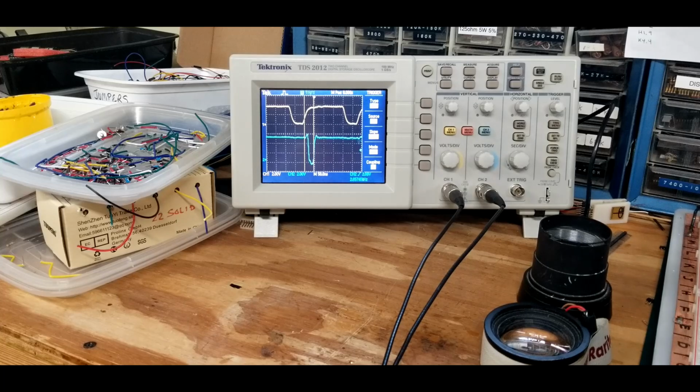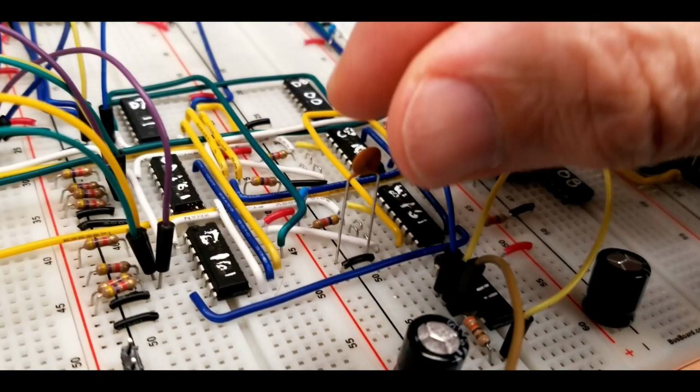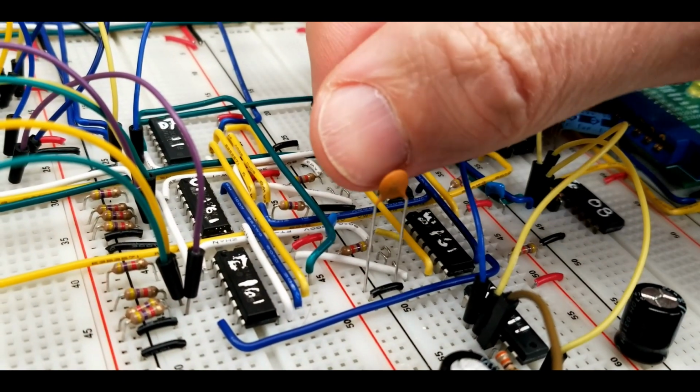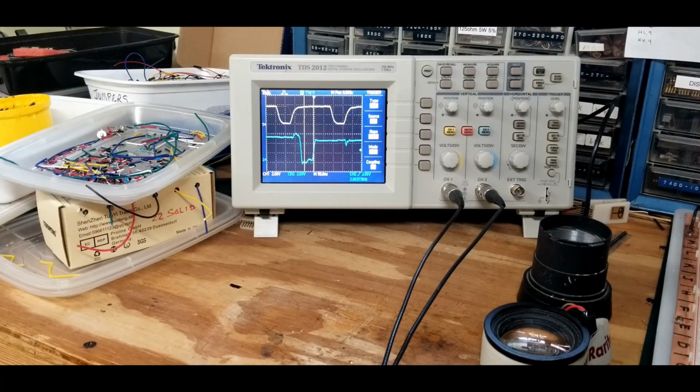Breadboard is not always a great environment, and signals can get dirty. I noticed that if I stick a .001 mic cap on any of these lines, the issue cleans up. This cap delays the signal a bit. You could also use a spare gate or two to delay this, but I'll just leave that in for now and do some digging offline so we can continue.